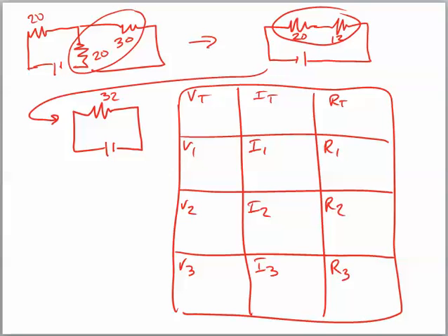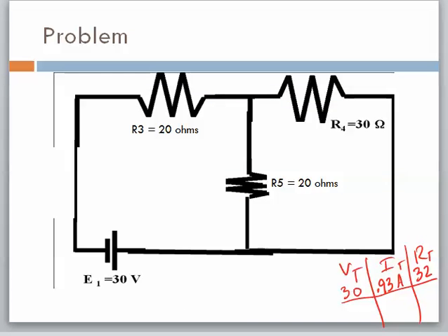So what I've created here is our chart. Hopefully you're with us to that point. Now I'm going to go back to the circuit that we have. We're going to start trying to fill in all of these components that we know. What we know right now is that this circuit is acting as if it's in series up till this point. Well, how much current do we know is going through it at this point? This is that third step where we take what we know and use our concepts. We know that the current is the same in a series circuit. So up through here, where this is a series circuit, we know that this is getting that set amount of current. So let's use that.